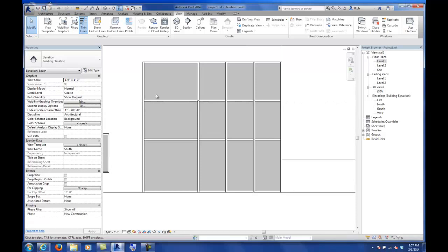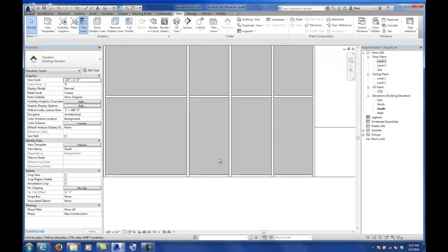All right. So we want to be able to place a door into this particular curtain wall assembly. One thing that we have to note is that we basically have to frame where we want that door to be, because when we place a door into this, it stretches and fills the whole entire frame, basically where the grid is set up.